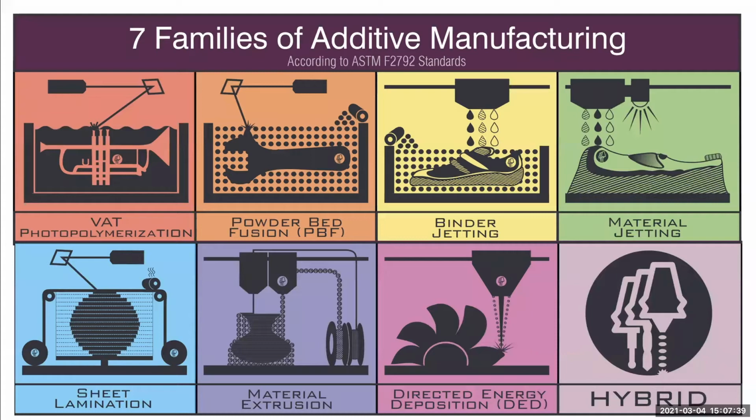So, if we're talking about slicing, and I kind of skipped that, but we'll come back to it in a second, that slicer basically just interprets what 2D plane is being represented by these three things, and then all the way up through all of this. Vat photopolymerization does one of two ways of drawing that: either a laser drawing an outline, which then solidifies that resin, or a larger image projected onto that vat of resin, which does the same thing at a larger scale, but it normally takes a little bit longer for that larger projection to work, so they're about the same.